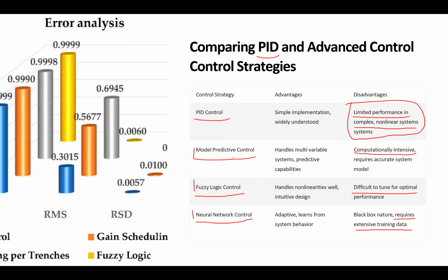So you can imagine the two sides: the output of the inverter is after the switches and before the filter, and the terminal is the place where you connect to the grid. So you measure the grid and you want to follow that. So that's your target. Now you have to change your values in the switching so you would follow that grid target. Did I answer your question?